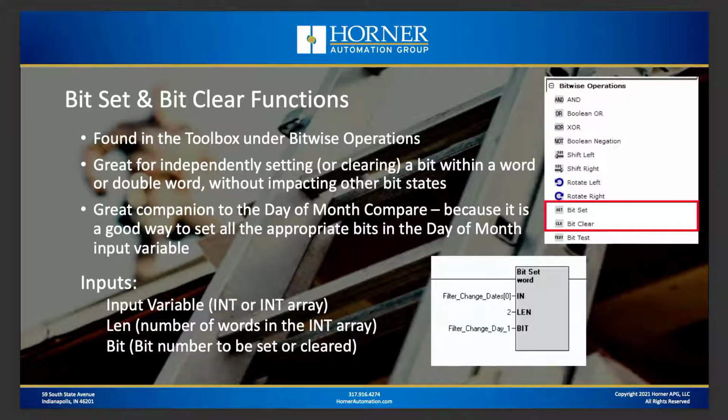Now these functions are great for independently setting or clearing a bit within a word or a double word, and it doesn't have to be just a word or double word. It can be literally a whole string of words, maybe that add up to 128 bits or 256 bits, whatever the case may be. Okay, so it's just a whole array of words, if you will. And it gives you the opportunity to go in and set a particular bit or clear a particular bit without disturbing any of the other ones. So again, that can be pretty handy.